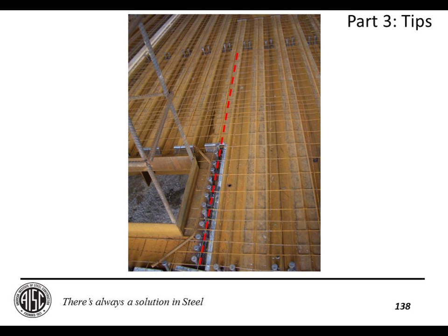I've also run into cases like this. For this particular instance, the span of the beam is shown by this red dotted line below, and the contractor welded all of his studs where he could in this nice little zone, one half of the beam. I asked him about this, and he was actually quite proud of himself because in this instance our drawing said 10 studs, and I believe that he had welded 13. So he gave me more than I asked for, unfortunately in a quite useless position.